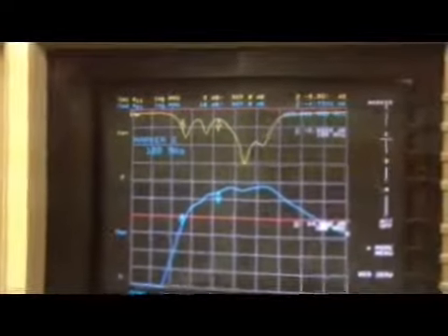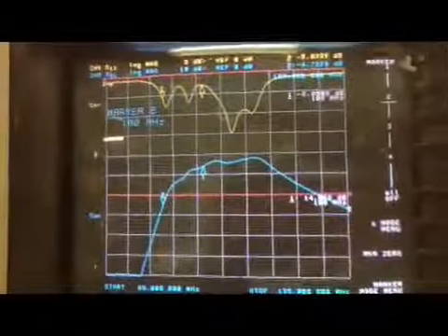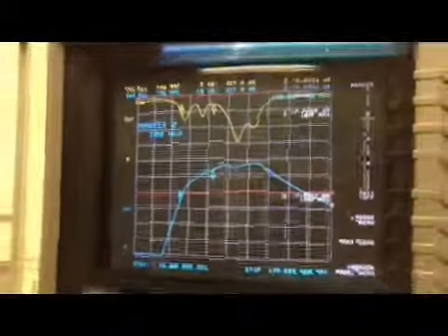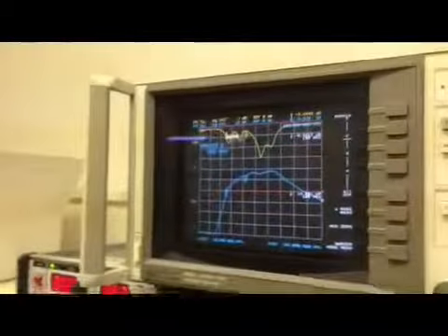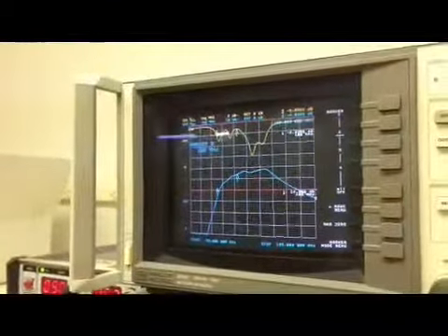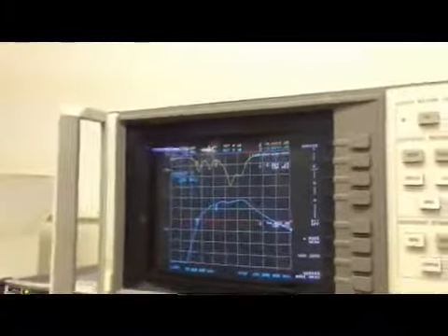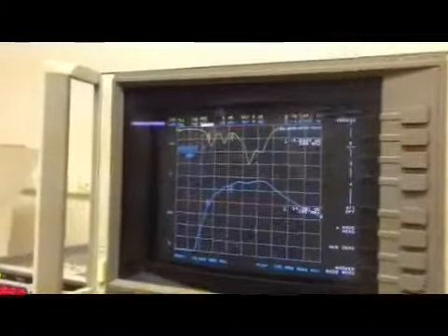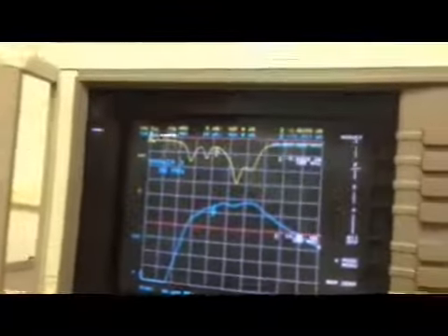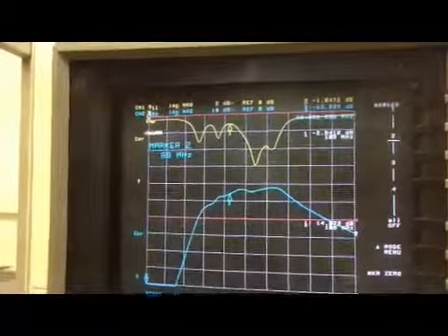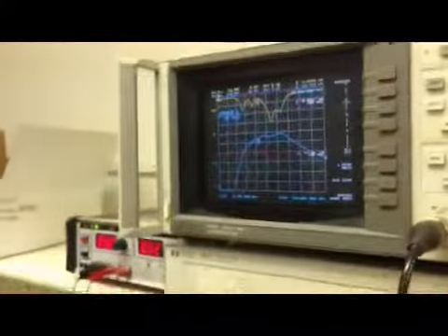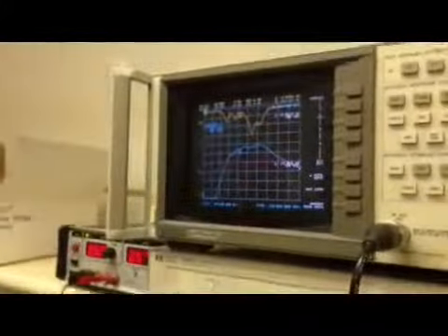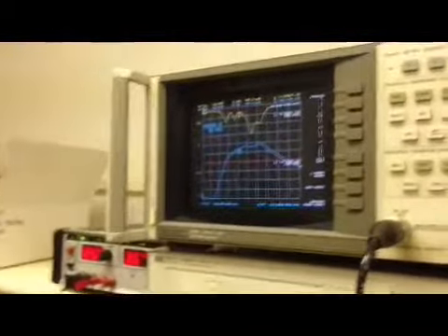So we're looking at over 25 dB of attenuation of radio frequency signals, which is rather good sized, especially according to FAA specifications through the TSO manual. And at the minimum, which is 88 megahertz, we can see that we're well below any detection point. That shows us that we are deep in the grass for the system, and being in the grass means that realistically we'd have to do some heavy digging to get a signal out of that.